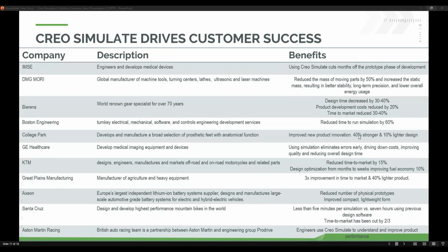This is a part, this is a bracket that would go onto a shelf in Costco or Sam's Club or something, and we've got a rod that would go through here and hold it up. This was designed in Creo. Basically, I created a sketch, extruded it symmetrically about the center axis plane, and I put a hole in it.